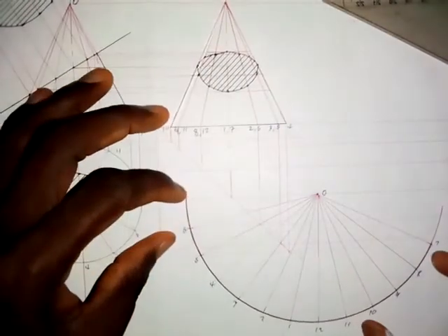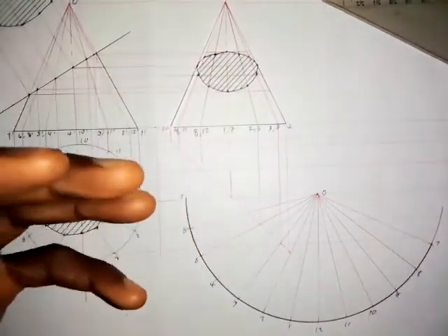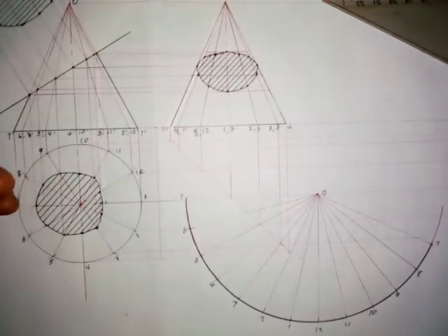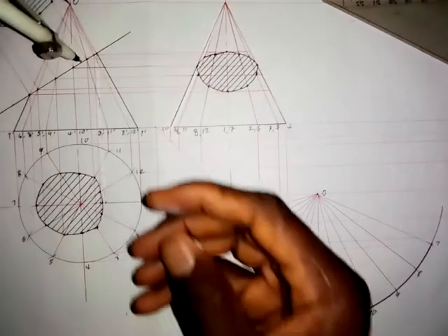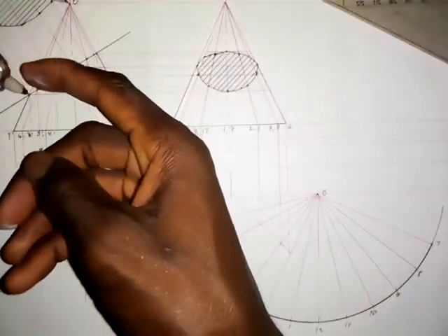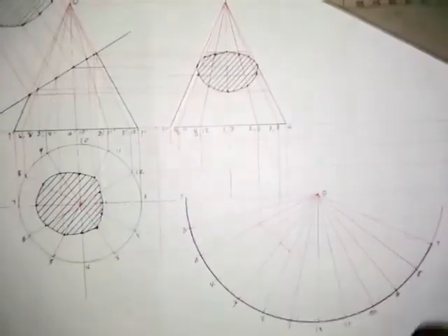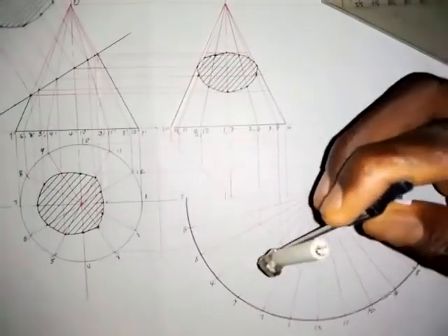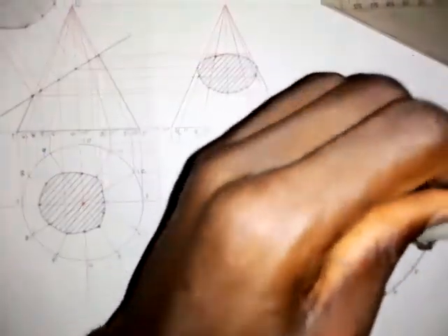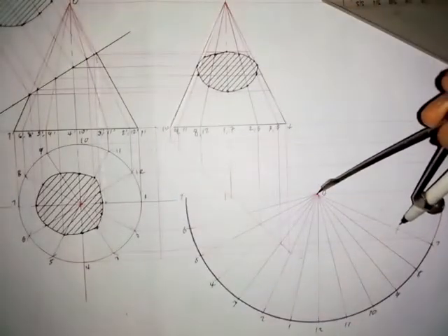All right, so the arc should be made thick because that is the circular base of the cone. So it has to be a thick line, as we have it as a thick line here, or a thick arc. So the next thing we are going to do is take your compass. Put it at point O here, and then you extend it to 7 here. Then you put it at point O here, you make an arc here like this, and then that is 7 on the right. So you also make an arc here on this 7 here.